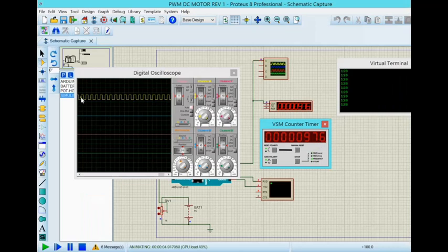How about the pulses? Looks like, I would say, 50%. That makes a lot of sense. That's the 128 that you see here. I'm using 1K here. Maybe I should make it larger, like about 10K. Maybe it still works. Let's see. If I go up, the off section should get smaller and smaller.